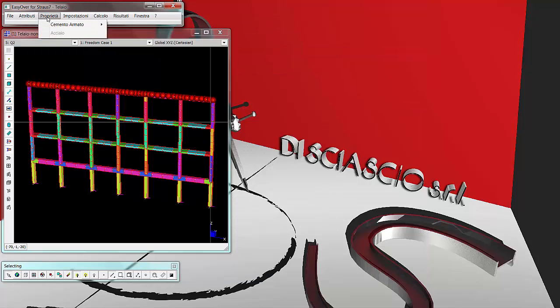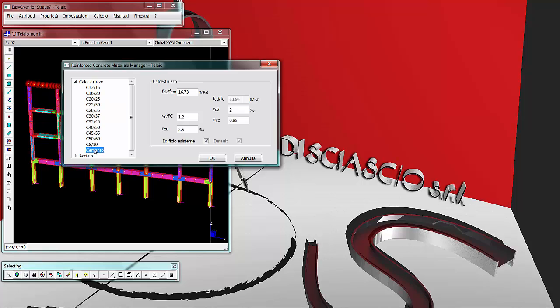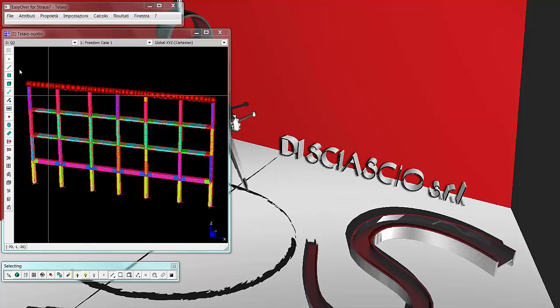In the Materials menu, the properties of concrete and rebar are defined, specifying, for example, whether it is a new or existing material. In the latter case, the mean values of strength obtained from in situ tests and from the additional sources of information on the building must be provided, together with the values of the material partial factors, depending on the level of knowledge achieved.